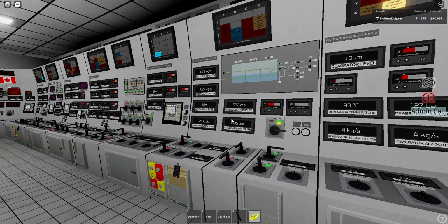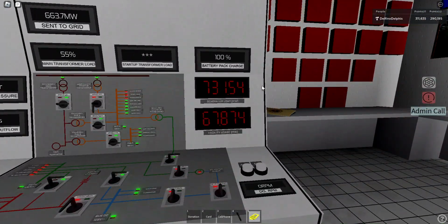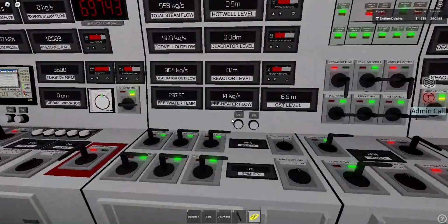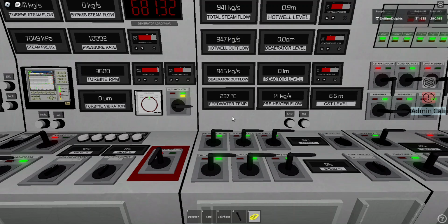If you tried to do it now, when you are doing this very high generator load, it will trip the turbine. If it didn't trip the turbine, without a proper load it would just spin up quickly and destroy itself. So this is why you want to match what you produce to what you consume, because this will help you keep the turbine at a constant RPM.